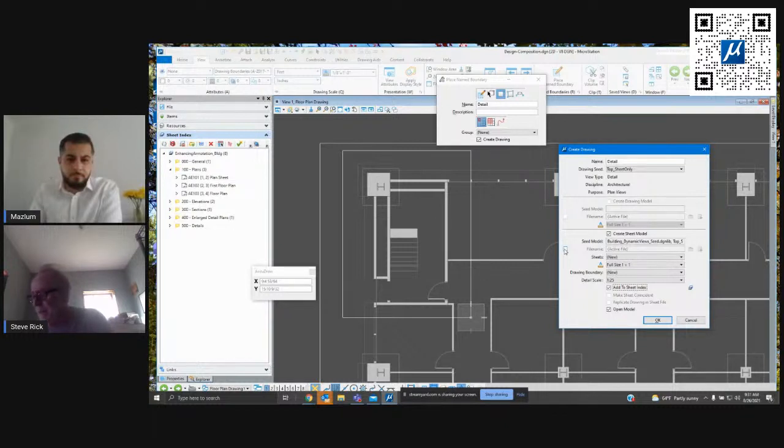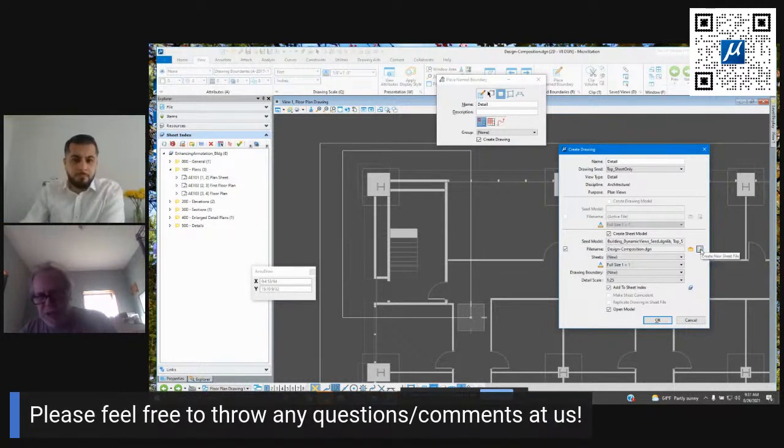There are a couple of my customers like U.S. Army Corps of Engineers, U.S. Army, things like that, and a number of DOTs that have to put one sheet per DGN. So from this dialog box, I can turn this on and create a whole new DGN, right? I can say create a new DGN, and every sheet I create is its own DGN. So I can put one model per DGN, just like they request. So I can put this in another file.